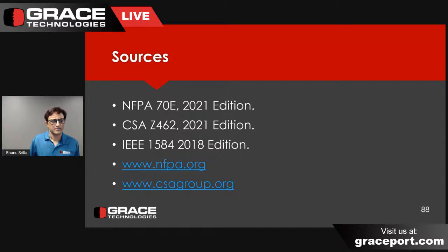Oh, fall arrest harness, ASTM F855. The fall arrest harness is automatically 40 cals, as long as they're ASTM F855, arc rated. Again, the comments I've made on the arc flash studies, there's not enough time to go into it, but you can contact me offline. I'm on LinkedIn, and I'll gladly talk to you about the problems with the studies. And I'll share a document that I have that explains the interpretation of the parameters.